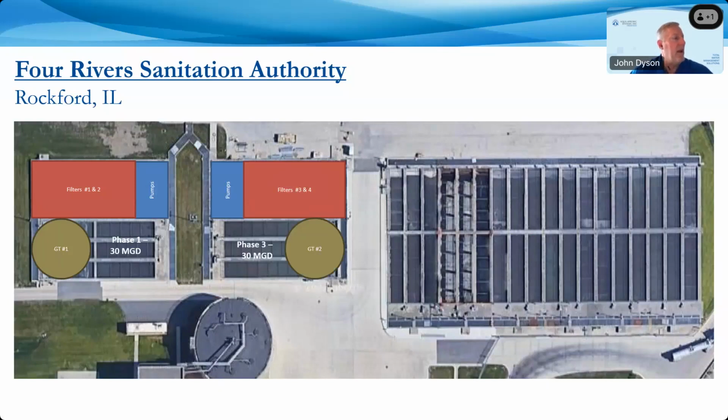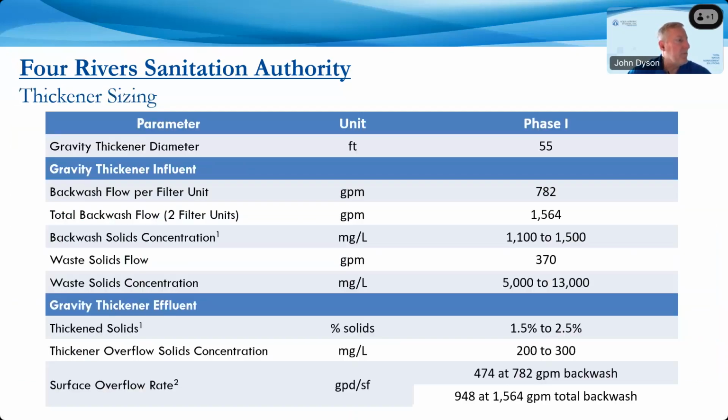After that, the plan is to undertake another 30 MGD of advanced primary treatment in the next set of two basins, and still have the remaining 6 newer basins available to handle really wet weather flow conditions once both phases of advanced primary treatment are completed.